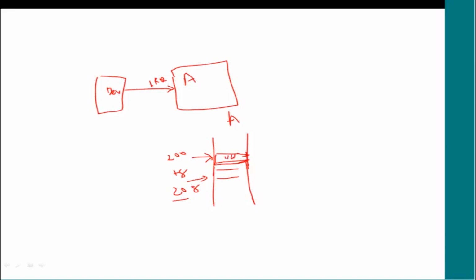So the processor, what does it do? It will first finish the instruction which is being executed. There are different stages, right? 3 stages are there. Whatever instruction is in the execute stage will be completed. At the end of the execution, the processor checks for the IRQ input, FIQ input, reset input, whether anything is there or not. It will be polling these bits.